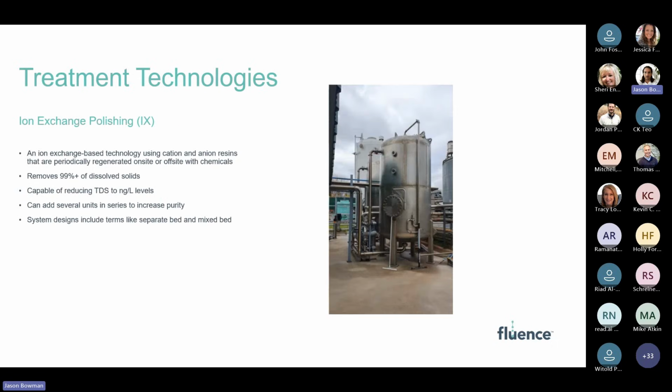Okay, so the final technology that I'll discuss today is a resin-based ion exchange system. In practice, these provide the same dissolved contaminant removal as EDI or CEDI, but with a resin-based ion exchange system, you can sometimes achieve much higher contaminant removal. The typical operation is to utilize an anion and cation in separate pressure vessels, followed by a final mixed bed polishing unit. The resulting water will oftentimes be suitable for your ultra pure type applications that would be necessary